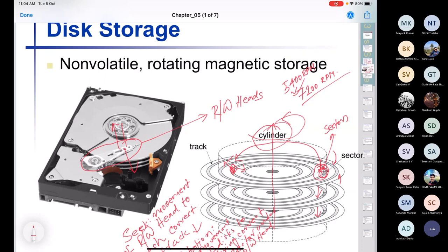That rotation is caused by the inbuilt motor, and that in turn needs a minimum amount of voltage to be able to rotate at that speed. So just cutting down on the supply voltage is not very easy.